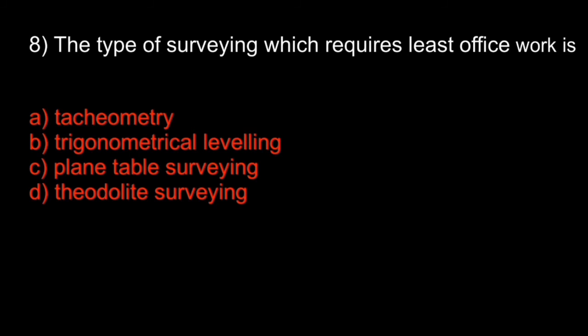The beveled edge of the alidade is called the fiducial edge, and there are two types of alidade, plain alidade and telescopic alidade. The accessories of plane table are a trough compass, a plumbing fork or U-frame with a plumb bob for centering the table, and a waterproof cover to protect the sheet from rain.